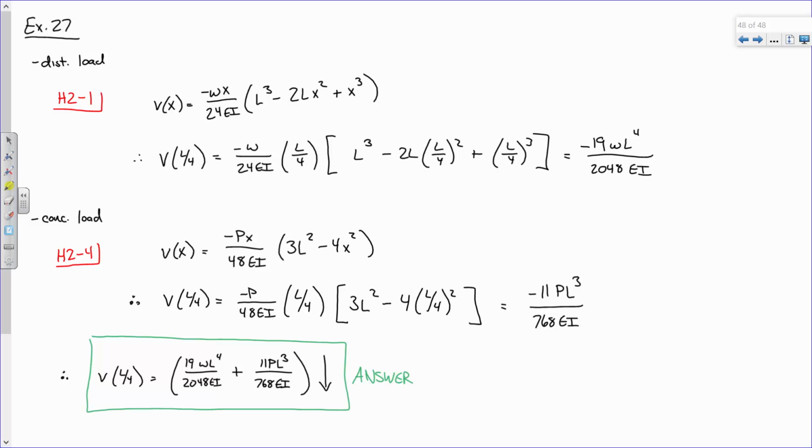But in all seriousness, when we look at stress analysis, instead of cutting sections normally, we're going to be cutting sections at an angle. So we're going to be generating normal stresses and shear stresses along a given plane. So how do you compute those stresses and determine worst case scenarios? Because what we're ultimately trying to find when we do stress analysis is a scenario where